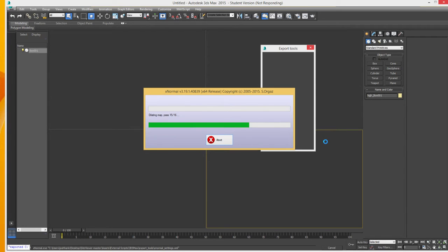So if it's white, it pulls the surface out in the direction of the face of the surface. If it's black, it pushes it in a certain amount. But that amount is arbitrary. You set that in Unity 3D, and also it depends how you decide the coloring of your map. All of which means when it generates the height map, it's best to have a little bit of user interaction.